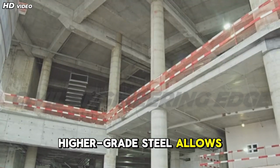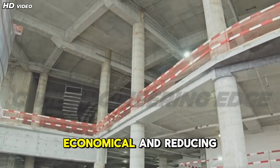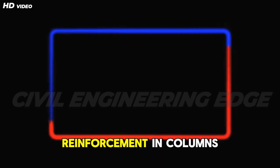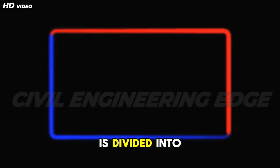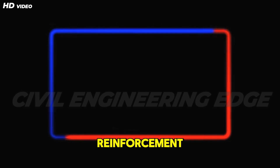Higher grade steel allows for reduced reinforcement area, making designs more economical and reducing congestion in heavily reinforced columns. Reinforcement in columns is divided into longitudinal reinforcement and transverse reinforcement.